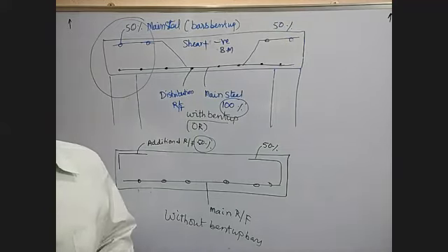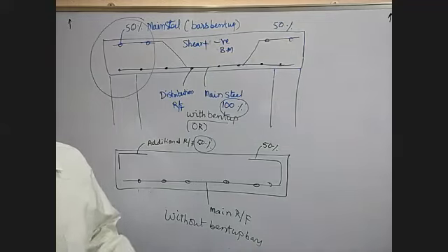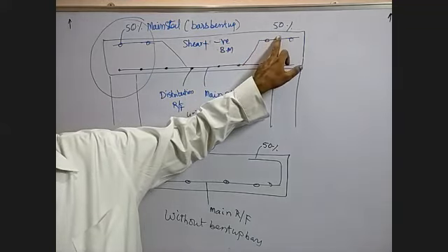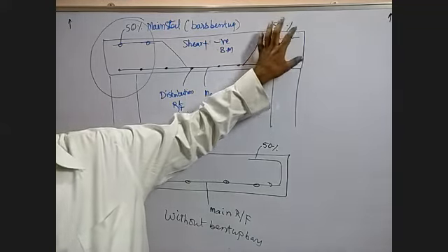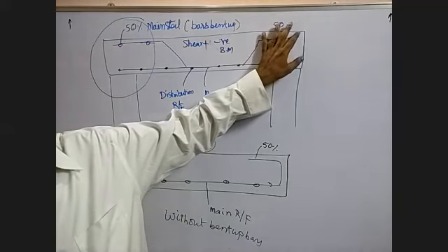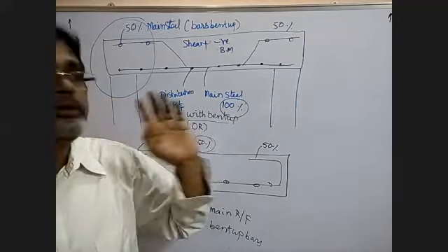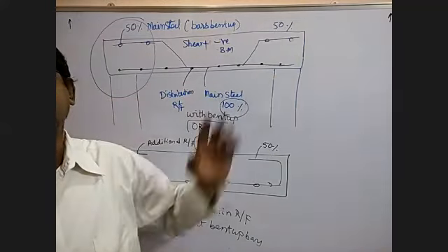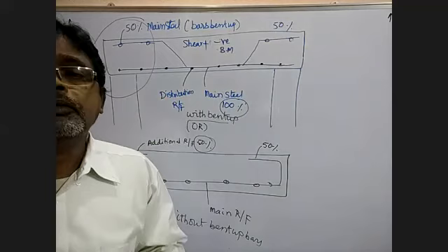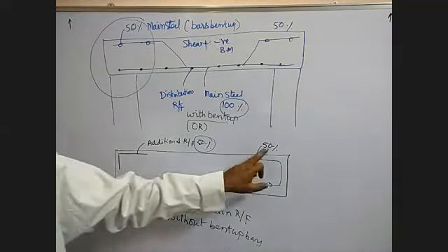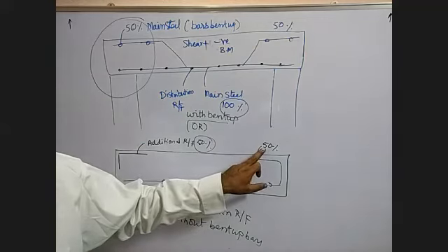It should be checked as per IS code whether it is within the limits or not. Even then, if it is not within the limits, you have to bend up the bar like this. It will take care of the shear, as well as the negative bending moment that develops here. In the beam, the bending moment is 0 here. But in the case of slab, you have a negative bending moment. That way, 50% additional reinforcement should be provided here.